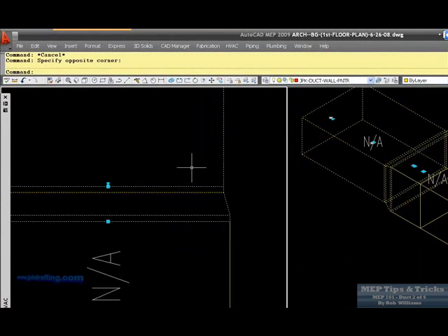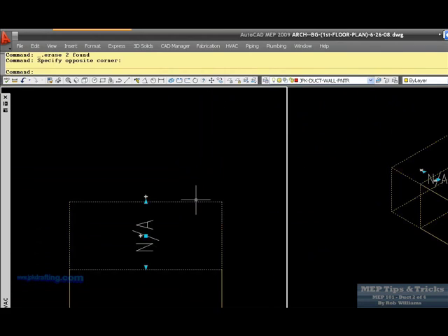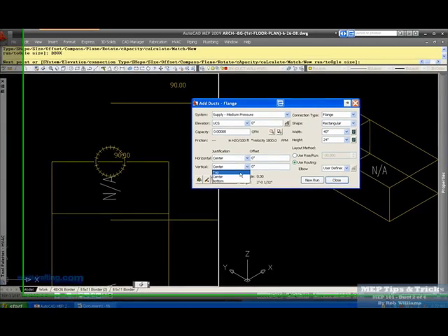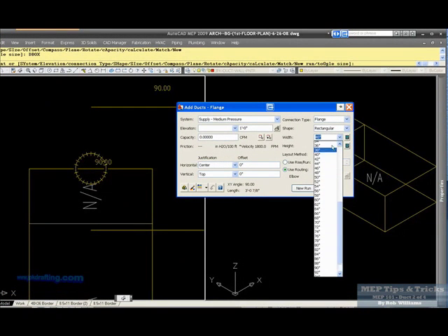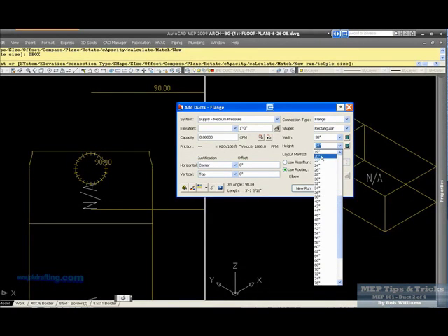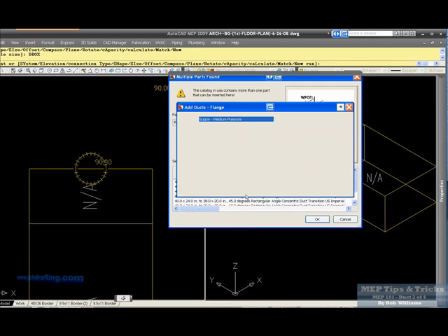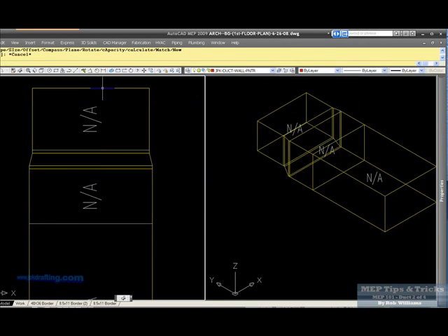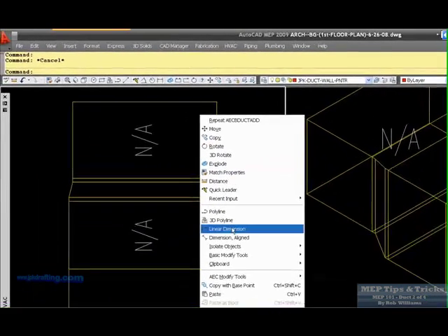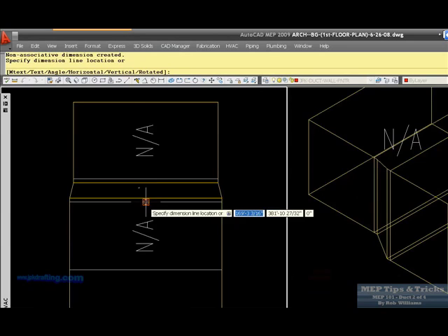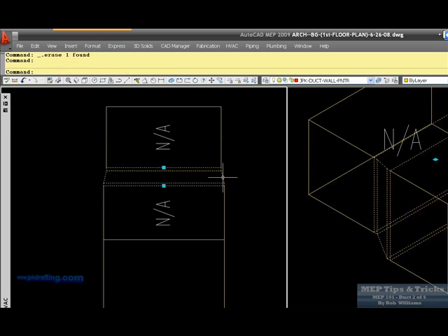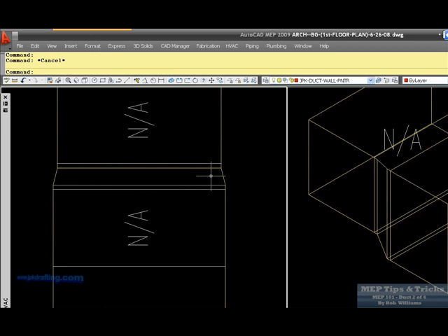Now you could choose to go flat on top on your auto routing. Come in here, go flat top, go 38 by 20. We'll go like that. And it does draw it flat on top. But you're not going to build that right there. 6-inch fitting. That thing will not survive. Too hard to get those into the Pittsburgh machine, and it just won't.